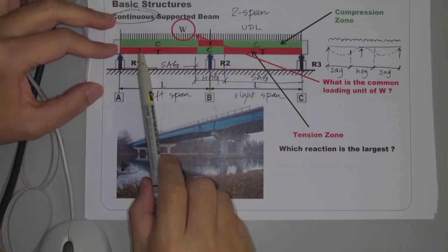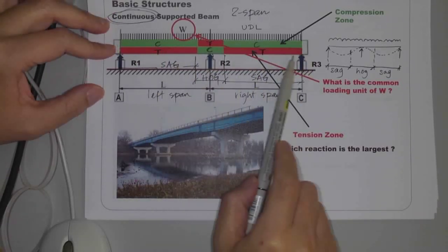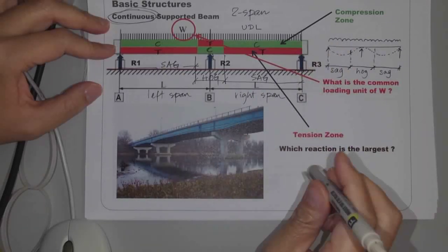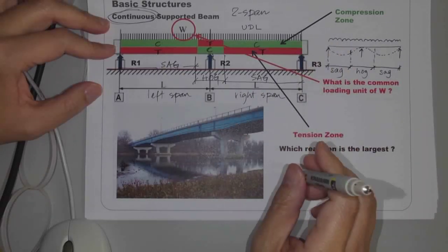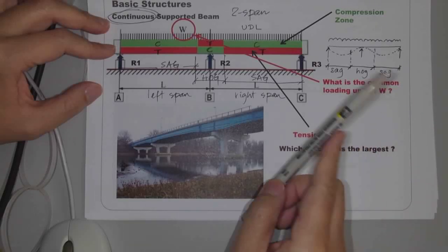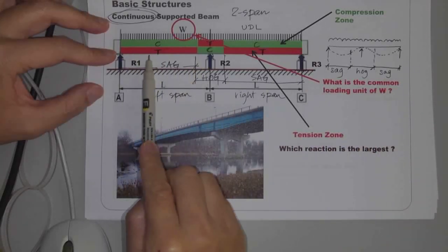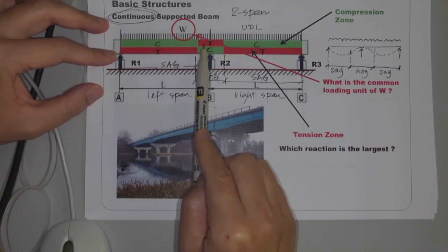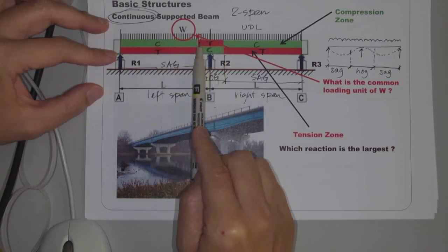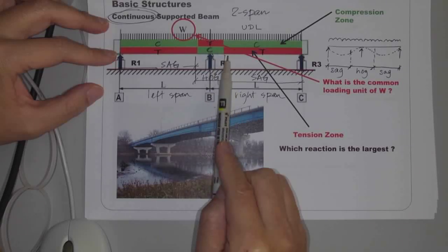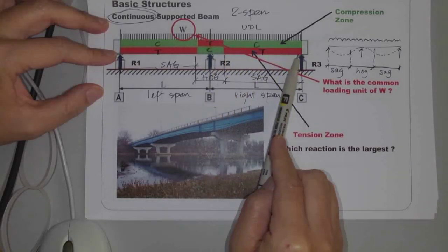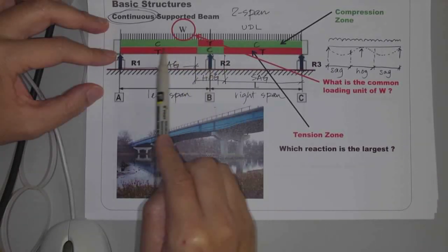So if I ask you if this is a reinforced concrete beam, you should be able to tell me where to put the main reinforcement. Where is the main reinforcement? It should be here in the tension part. Then it goes to the top. Then it comes down again. Those should be the places where you have main reinforcement.